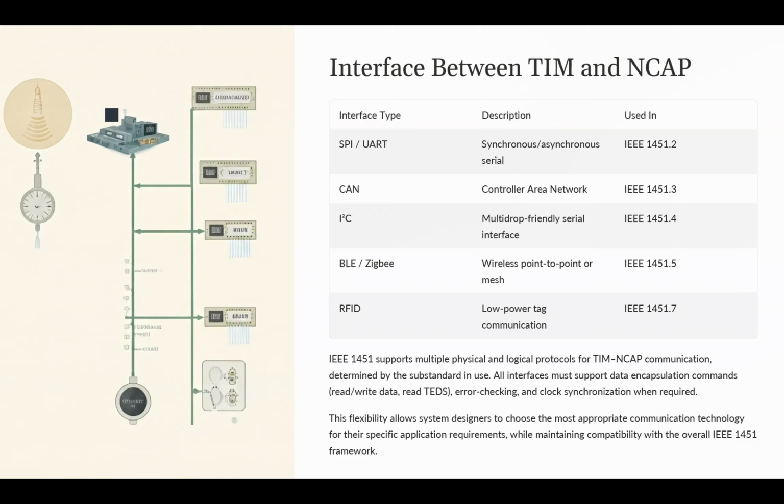Now, we have BLE or Zigbee, which is the wireless mesh or point-to-point connection between TIM and NCAP. Part 5 of IEEE 1451 covers that and basically defines the wireless interfaces that enable remote TIMs to interact with NCAP, with applications in mobile, wearable, or smart infrastructure systems.